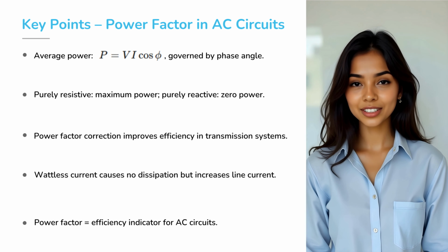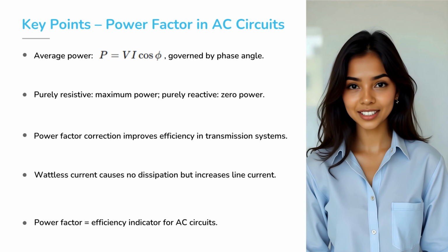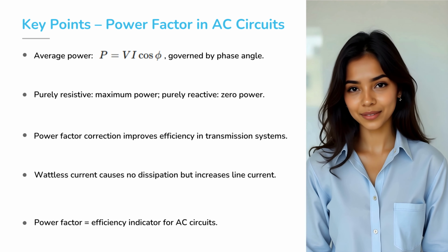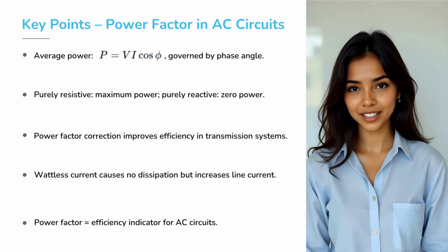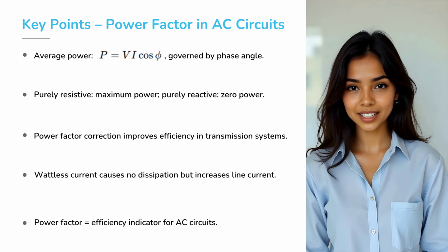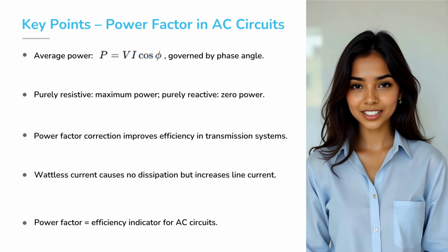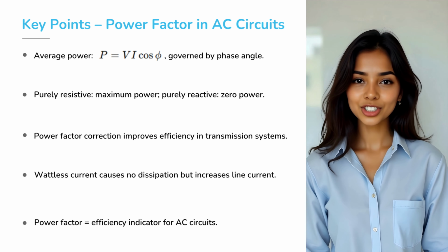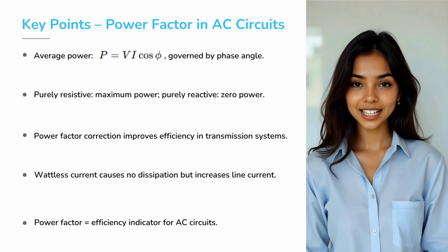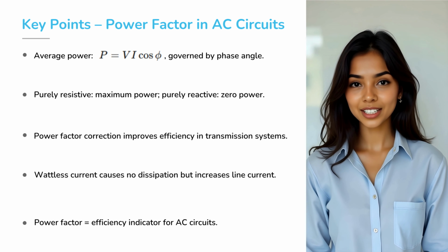Improving power factor is crucial for reducing energy waste in industries and transmission lines. And remember, wattless current may not cost money directly, but it increases current in the lines, causing unwanted heating losses. I hope this session helped you see how the power factor connects the geometry of phases with the economics of electricity bills.